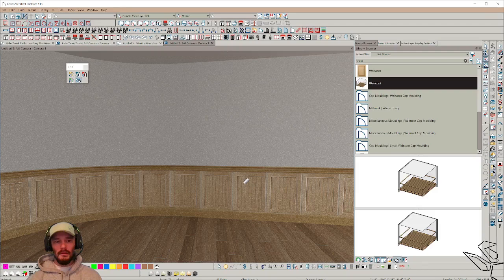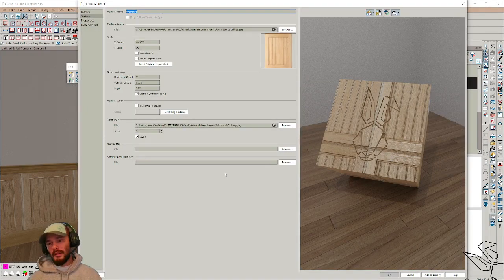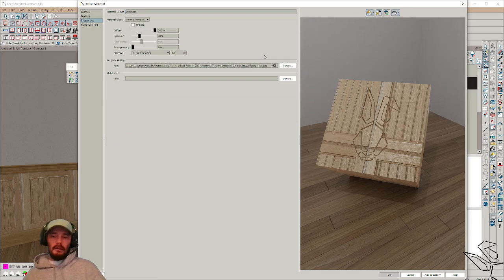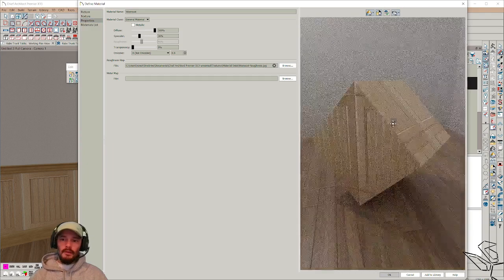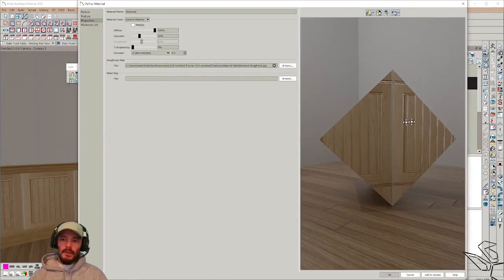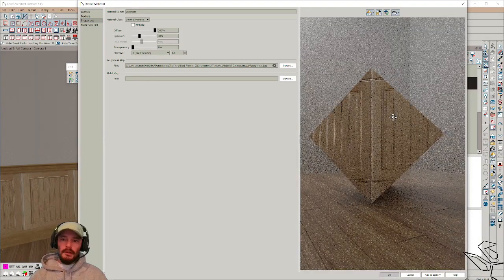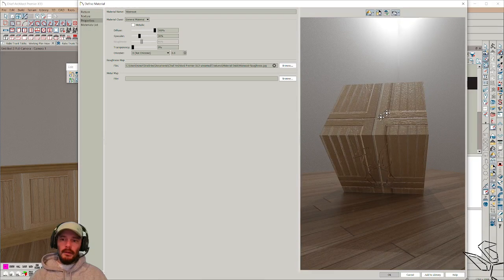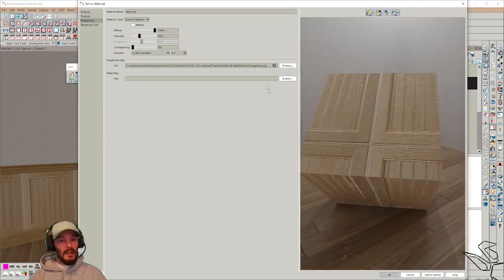If we turn gloss off, and keep in mind, issues with gloss will usually iron themselves out if you increase your sample rate on your image exports. A lot of times, if you pump it up to something like 5,000, a lot of times those glaring issues where we're seeing way too much gloss in our bump maps, right? Those issues can get ironed out when you increase your sample rate.